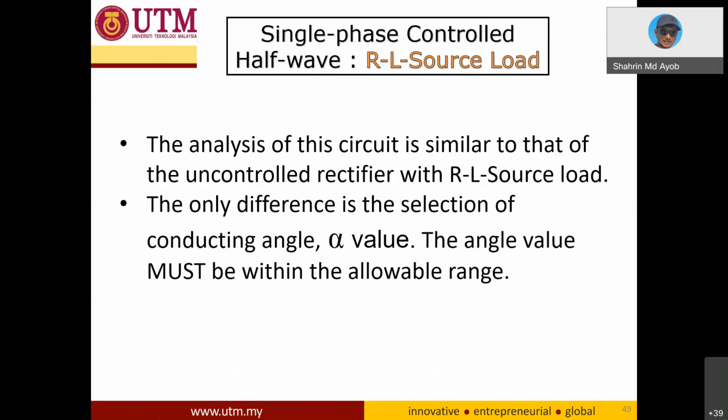Okay, the analysis of the circuit is very similar to the uncontrolled rectifier with the RL load source. The only difference is the selection of the conducting angle alpha. The angle value must be within the allowable range, which has been shown in the slide.